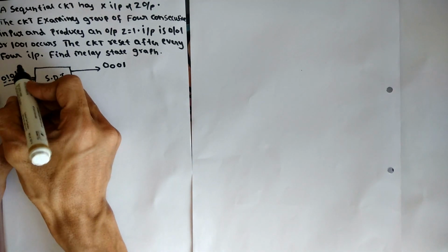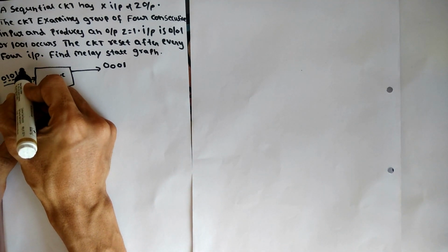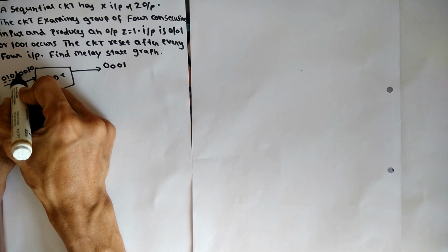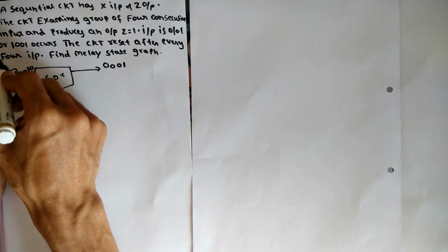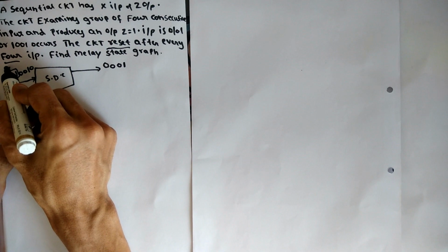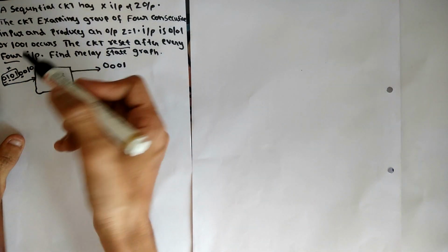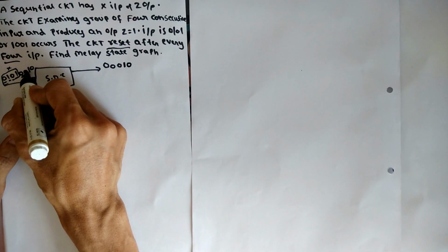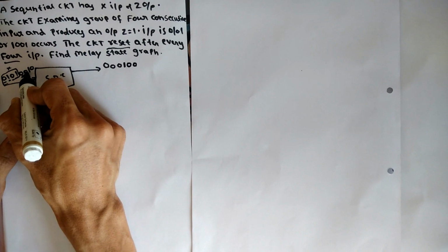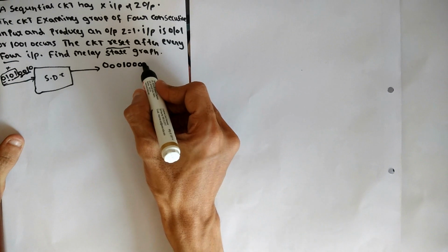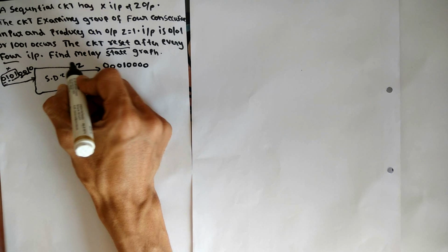If you give some other numbers in a similar way, 0 0 1 0, what happens in this case? It will not consider this 4-bit group further, because after 4 inputs it has to be reset. So we are not considering anything after this. We have to start from a new 0 here. The new 0 is anyway not a complete sequence, so 0. Again we consider this 0 0 0. Then 0 0 1 is not there, and 0 0 1 0 is not equal to our sequence. So it is 0. Like that we will get the output Z for the given values.